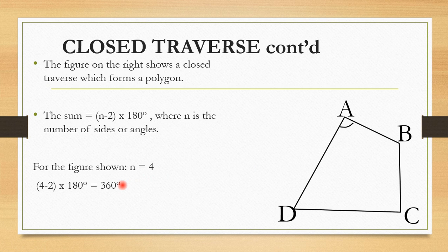So we normally do the adjustment of the angles where the difference is just a few seconds, because however experienced you may be, it's very difficult to come up with a perfect polygon after the traversing. So we determine the adjustments whenever you have a difference which amounts to a few seconds and not necessarily minutes or degrees of an angle.